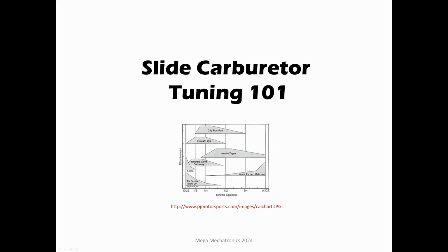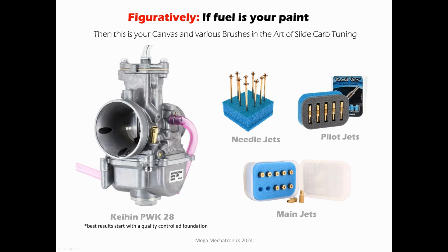So he used a ball valve to adjust the amount of fuel flow into the carburetor to match the airflow. And he just used his senses to set the right ratio for that RPM and load of the lawnmower, spinning the blade. So there's that story. Okay, let's move on here.